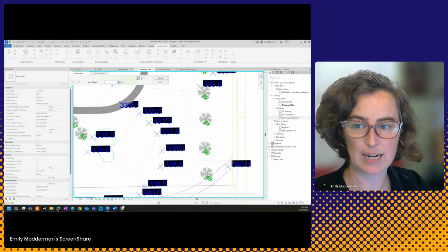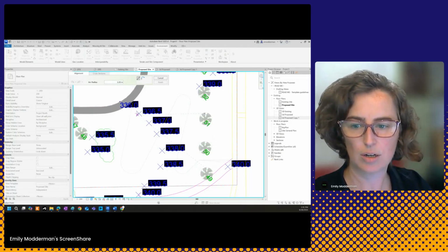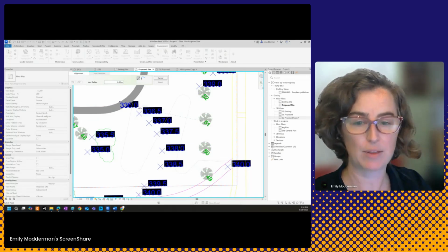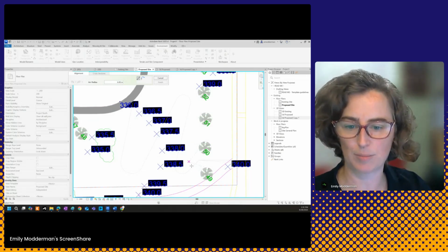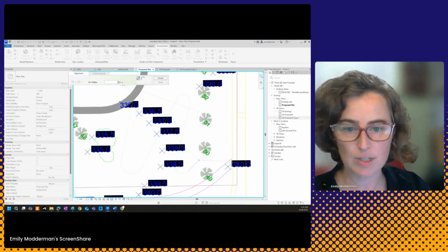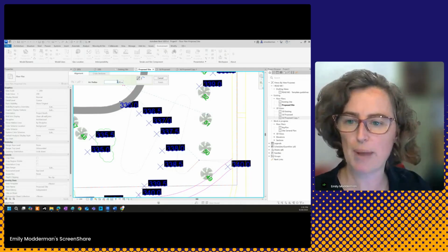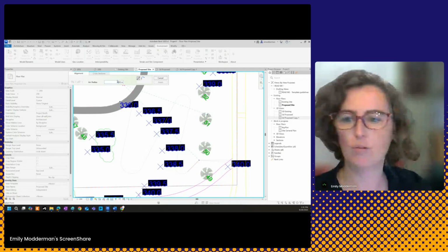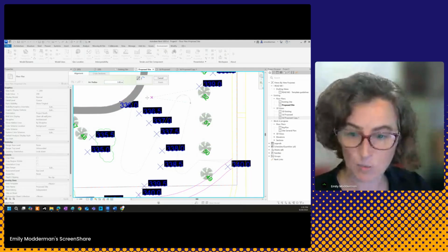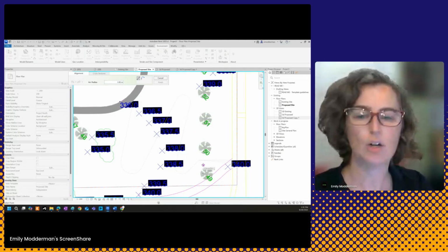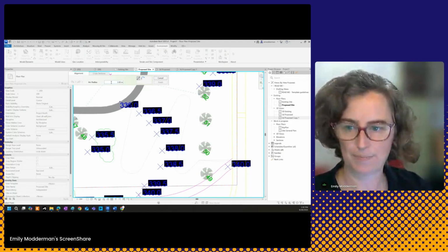And I can set a radius. Now, just a tip about your radius, based on your pathway requirements. If your pathway is going to be 6 meters, then a radius of 6 meters is reasonable. My pathway is going to be about 3 meters. That's, I think, the minimum accessible width for a pathway. So I'm going to, in this case, match my radius to 3 meters. Now, I'm working with a pretty tight scenario here. But that's really the minimum of the radius that I can go for.